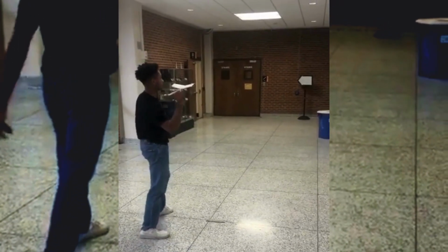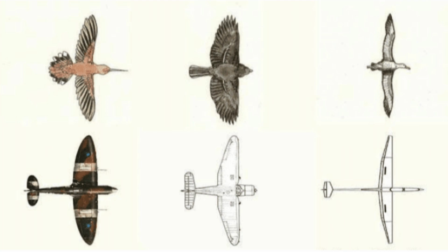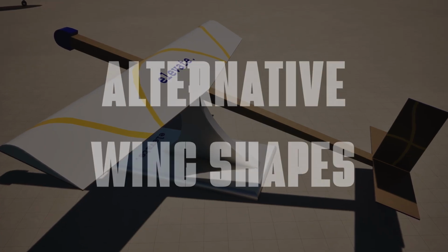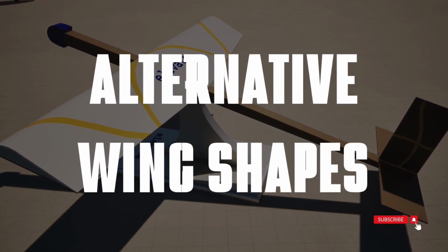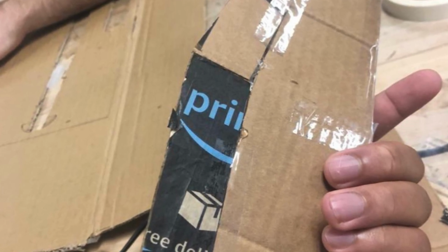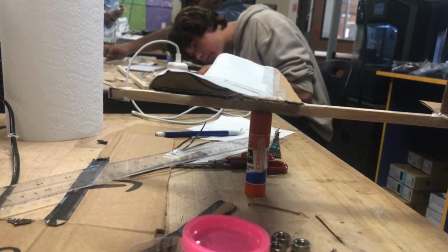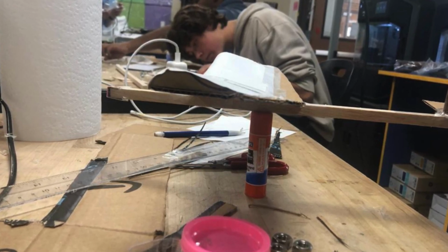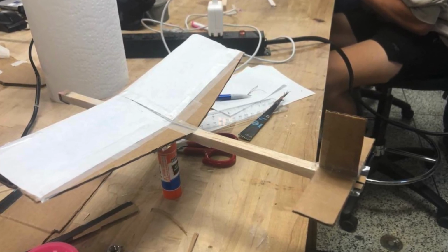Through a series of over 10 test flights, I discovered that the glider didn't generate enough lift for the 20-foot minimum target. Now it was time to investigate alternative wing shapes. So to improve the lift capabilities while keeping the 16-inch dimension limitation in mind, I added some more wing area behind the initial wing. After doing some more testing, I was satisfied with the amount of lift being generated, but the extra lift amplified a problem that I had not initially seen.